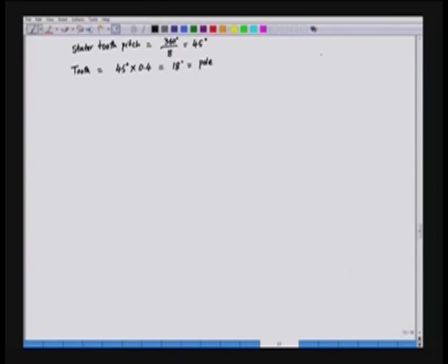So, it means this is the rotor pole, and if we linearly develop this, this angle is 18 degrees. And the stator tooth pitch is here 45 degrees, which includes the tooth and the slot. So, this is 18, the tooth is 18 and tooth plus slot is 45 degrees. So, what is the slot here? This is the stator tooth.